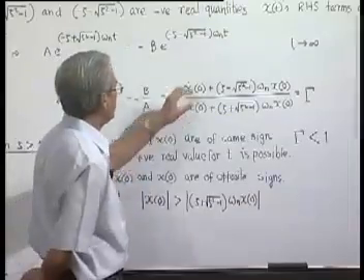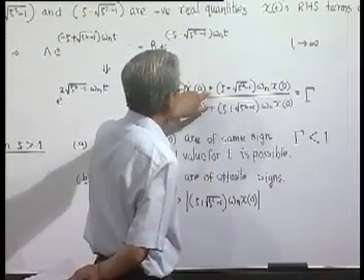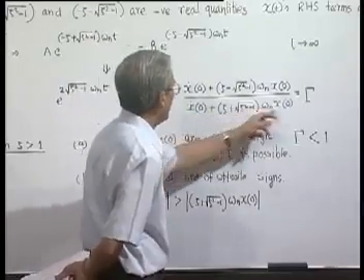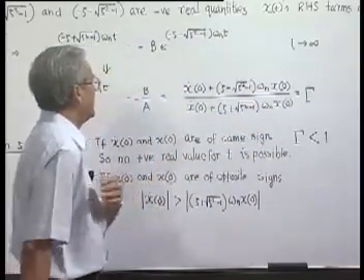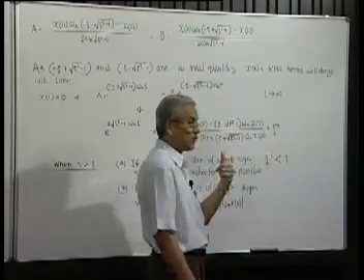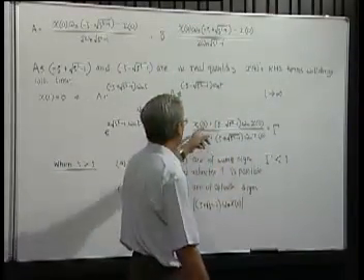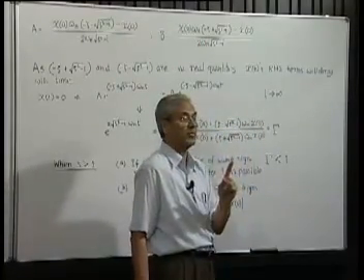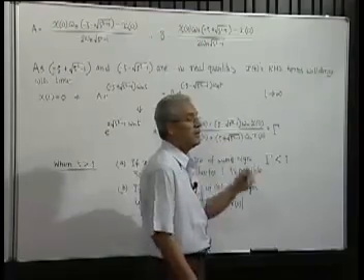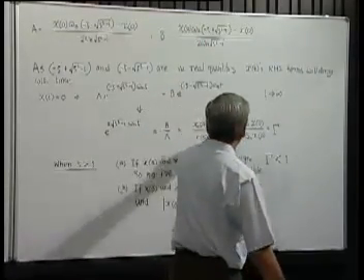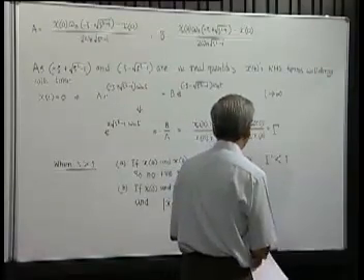So what we are getting is x dot 0 minus a quantity, and below, x dot 0 minus a quantity which is larger than this. So what will happen? The numerator will be a positive quantity, the denominator also will be a positive quantity, but this will be less in magnitude. So that means gamma will be more than 1.